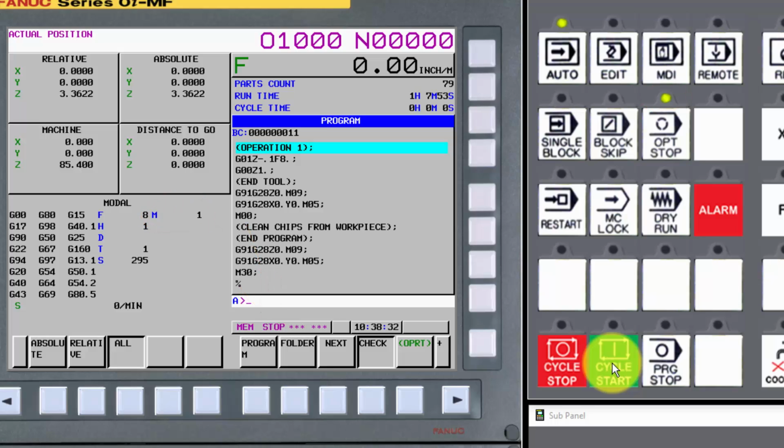It is very common to include an M01 at strategic points in the program, such as tool change points or at the beginning of an operation. These can be helpful when initially verifying a program, or to stop the program before some process maintenance, such as inspecting a tool and checking the coolant levels. In normal operation, the optional stop button is turned off, but the operator can turn it on at any time they want to stop the program at one of the safe stopping points.